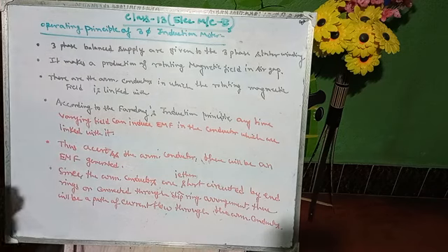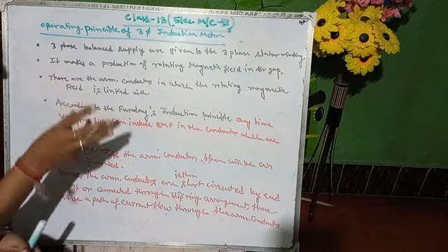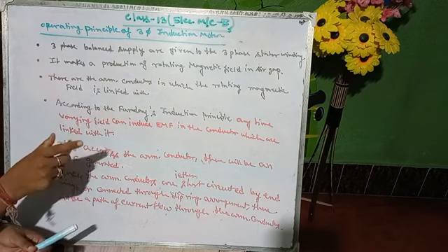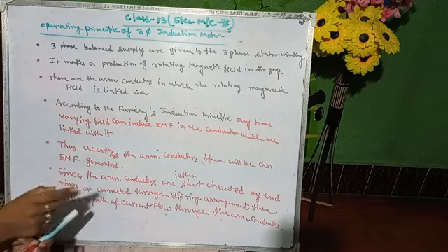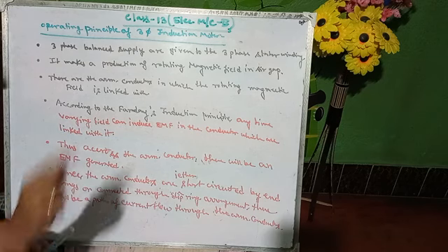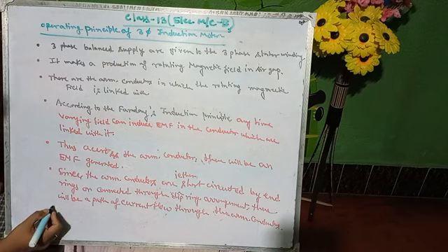That means a three-phase system can produce a rotating magnetic field inside the air gap, and this rotating magnetic field is linked to the armature conductors, and since the armature conductors are short-circuited or connected through some slip ring arrangement, a circulating current will flow through them.